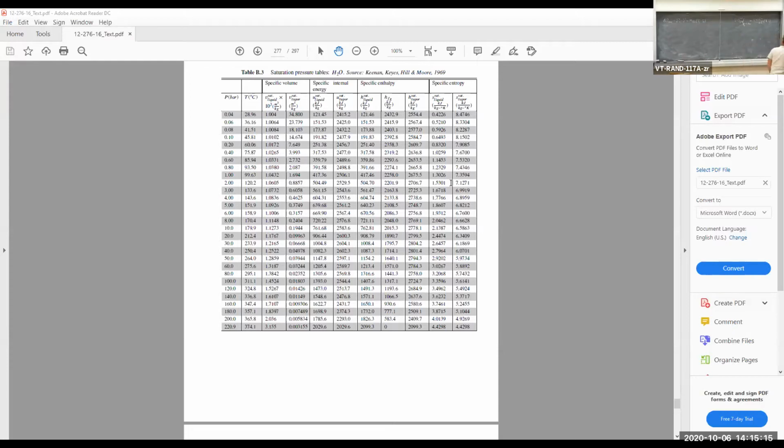Okay, so I have S1. There we go, that's a help. Now what about S2? Well, that one might be a little bit harder to find. I need to know something about state 2. I need several things. I need 2 properties: a pressure and a temperature, or a pressure and a quality, something.